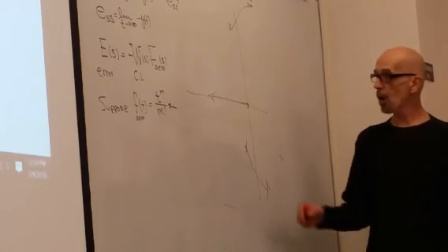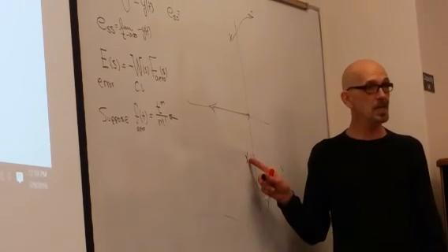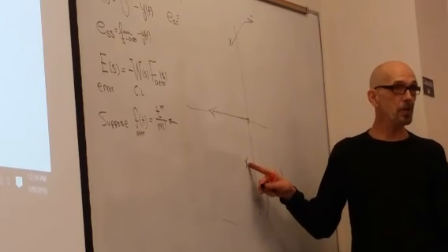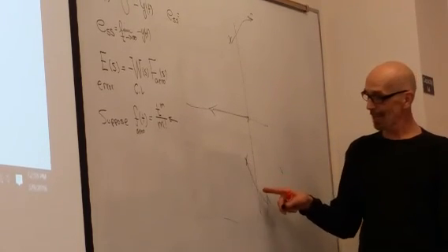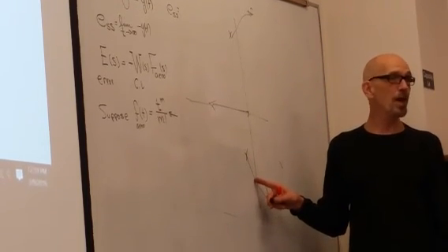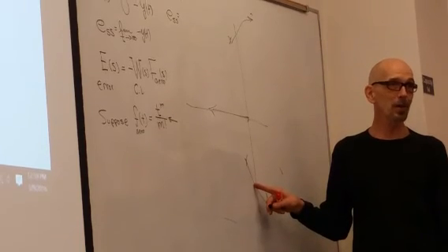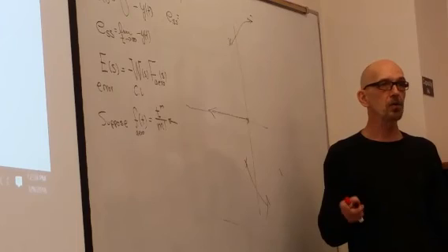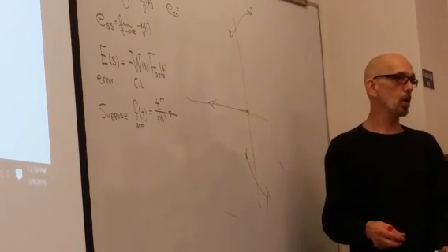This controller, for small k values, will stabilize it, but will it reduce the damping? No, the damping is going to go up. In fact, if you have controller drift, your plane's dead. So we know that this controller, just simple integral control, isn't going to work.